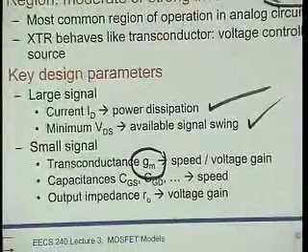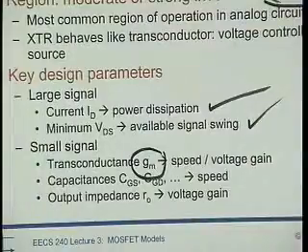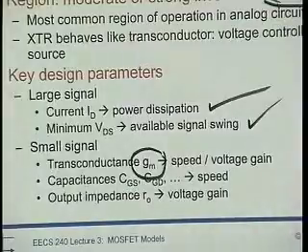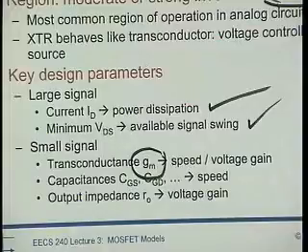Transconductance. Well, most of the time, why do we use transistors? Well, we want to make amplifiers. GM is the gain. That's the currency of how good our amplifier is. That should be infinite. Okay? And it determines, lastly, how much voltage gain we can get, and even more importantly, how much speed we can get out of this thing. If GM is infinite, we can build infinitely fast circuits. So we want to know something about GM.